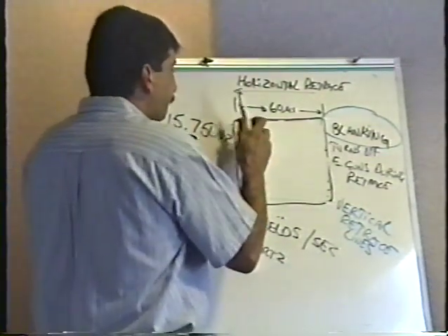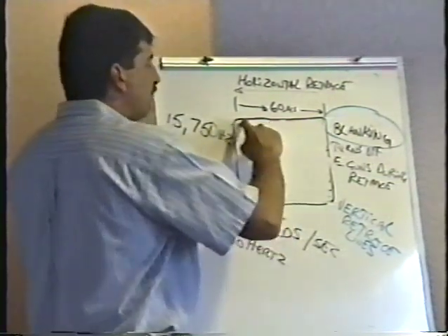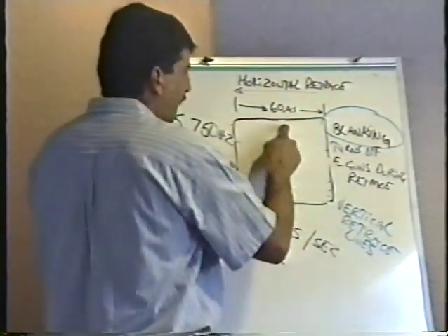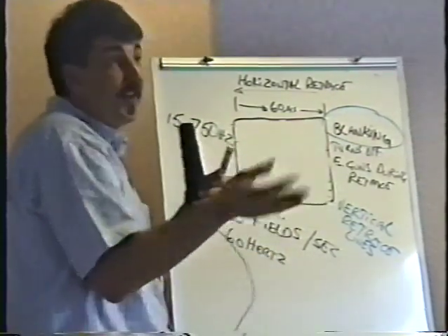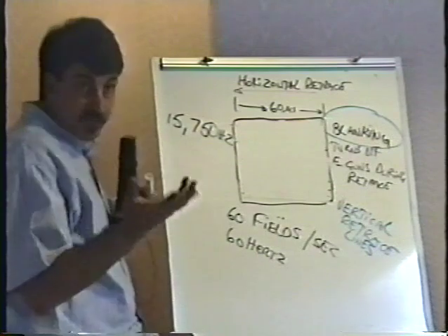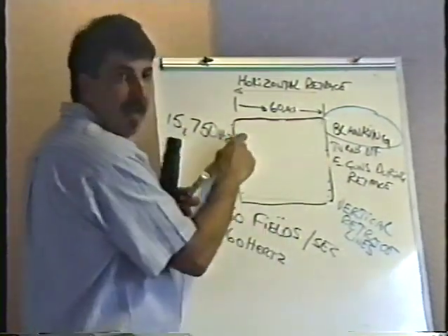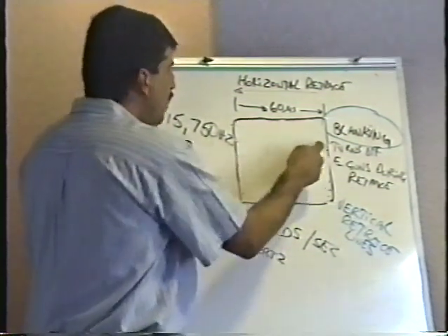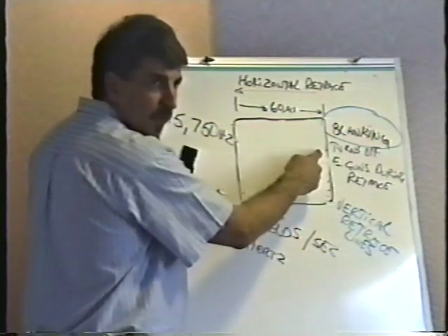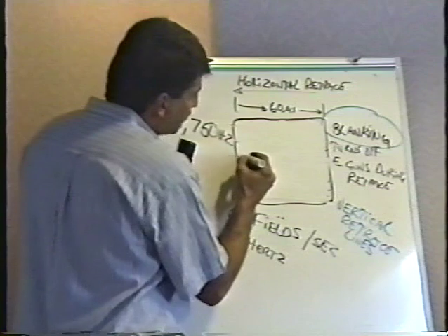And we just want to draw a box in the middle. So as the horizontal deflection coil makes the beam move from left to right, the beam is kept turned off. So it isn't really a beam at all. The magnetic field thinks the beam's there, but it isn't really. It's turned off. Of course, it's always off on the way back during the retrace time. No shortcuts allowed. No matter what we want to show on the screen, it has to start out here and start scanning. It's off, it's off, it's off.